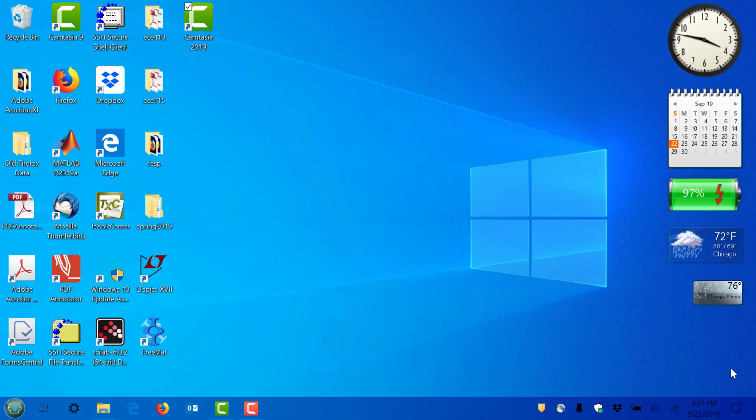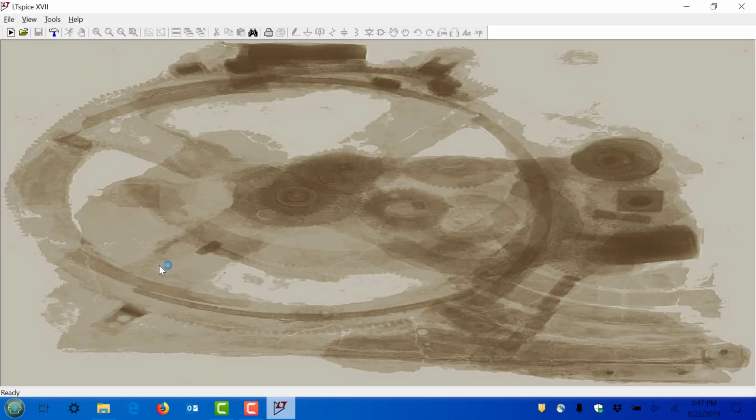So if LTspice is installed on your machine, including the ones in the lab, to start it, simply go to the LTspice icon over here and double click. When you double click, you will see this background image. However, if this is the first time you're launching LTspice, you might have some startup options that have to be executed for about a minute or two. That's perfectly all right. Just wait, and when it's completed, you should still see this picture with this background.